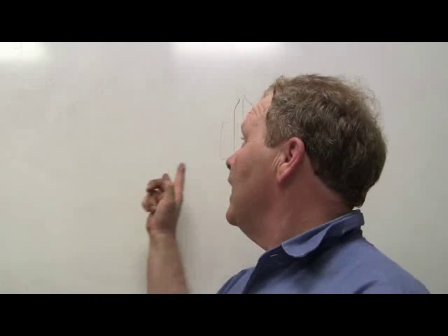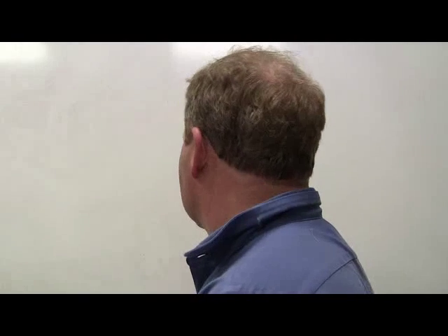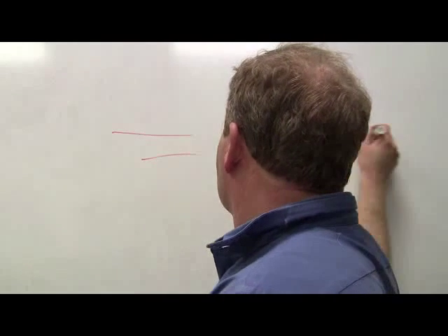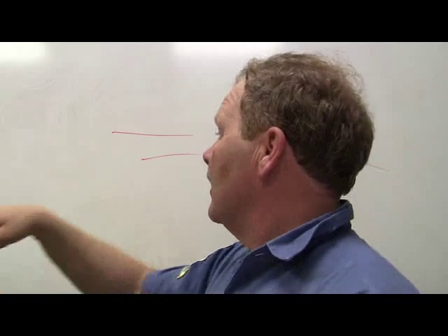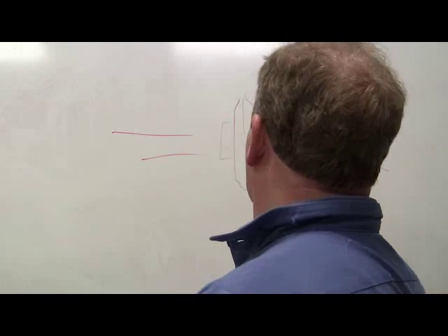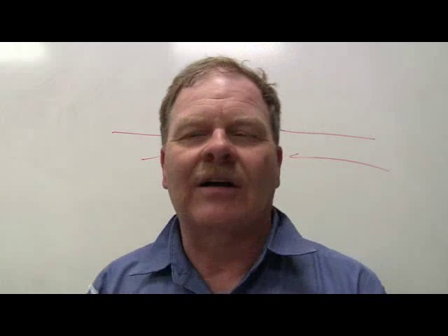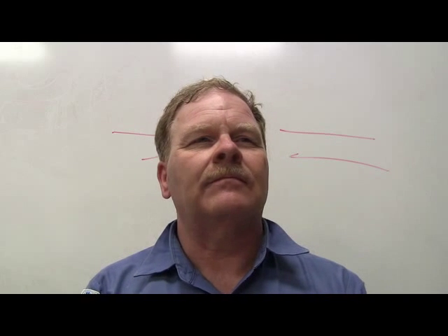That thing that you put in there, you're going to leave it in there for 30 minutes, then take it off and throw it away, and put another one in there. The screen is going to stop all the crap from going anywhere. It's going to capture it. Yeah, it's actually in the liquid line. So it's going from the condenser to the evaporator, but you're stopping that trash right there.